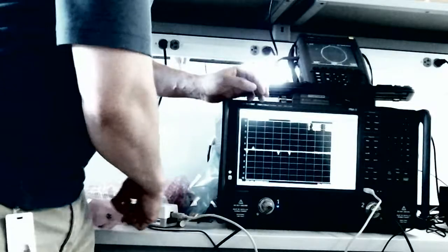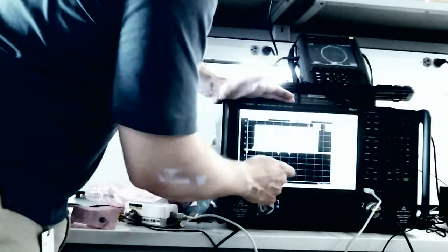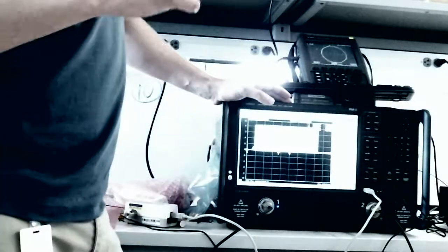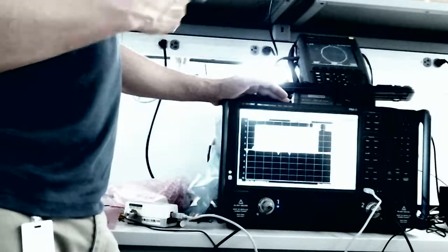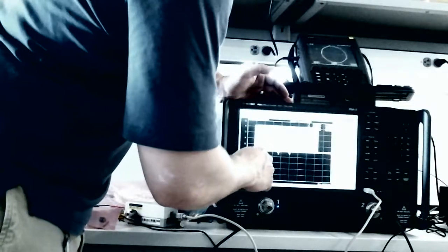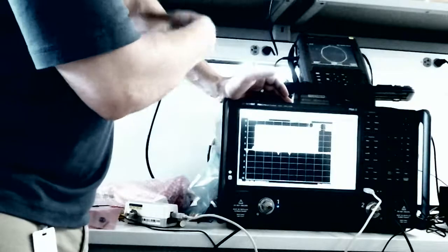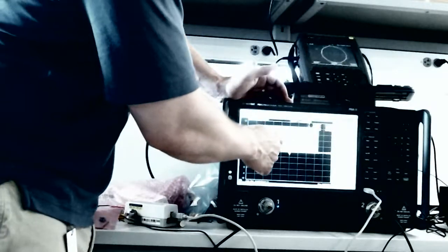So let's go into the measurement, and I'll just talk about this pretty quick because I don't want to spend too much time on it today. When I bring in an actual LNA, let's do the measurement, and then I can show you guys how to do that. So under noise figure cold source, I'm just going to hit OK. Because if I didn't click a new channel, it gives me the option of overwriting this. That's what I'm just going to do for now.